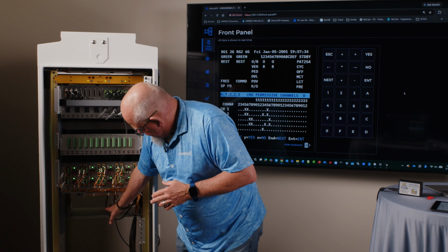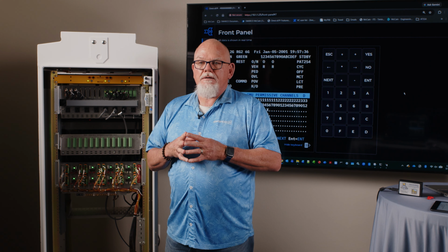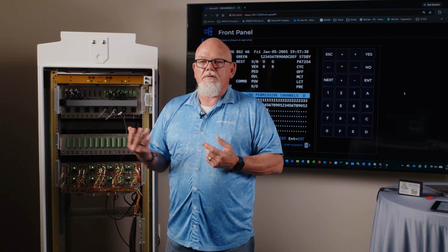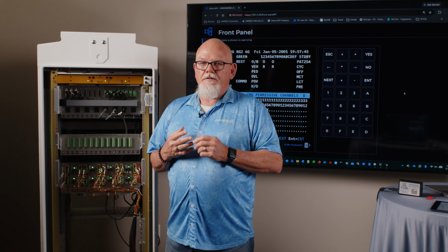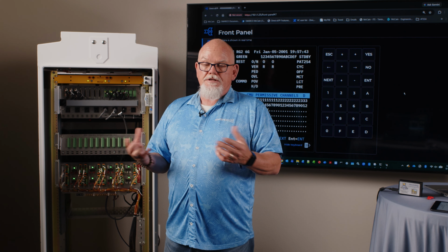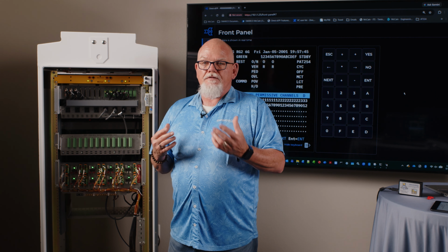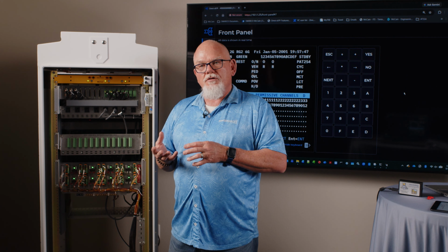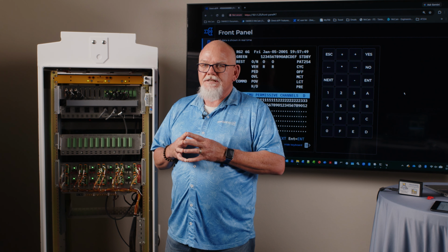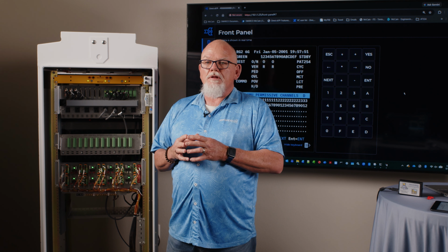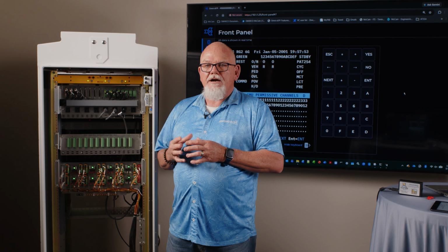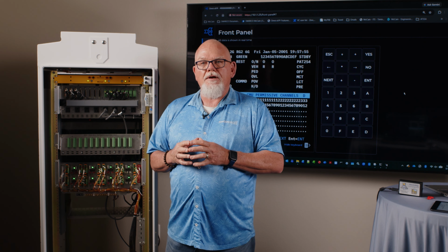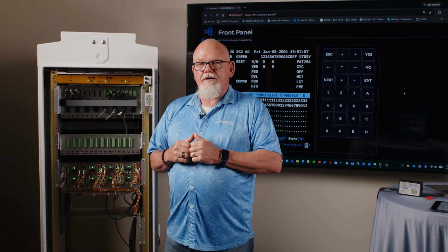Below that, you see the backside of our power distribution assembly. The backside is where we bring in the wires from a service assembly or a service meter pedestal to provide the AC to the cabinet. It's also pre-wired for battery backup systems. So no more extra plumbing for wiring up battery backup systems. These cabinets are all ready to go for battery backup systems.